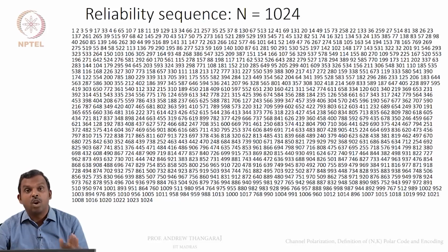And also, if you read more, you will see that if the noise variance changes in the AWGN channel, this reliability sequence actually changes. Okay. So, it's hard to pick one reliability sequence for a wide range of noise variances, but people use close simulation studies and carefully study it and come up with something like this. Okay. So, the reliability sequence is a difficult thing to find.